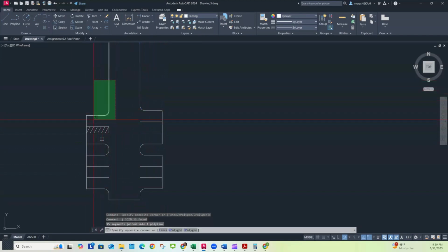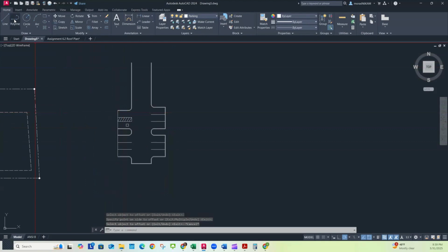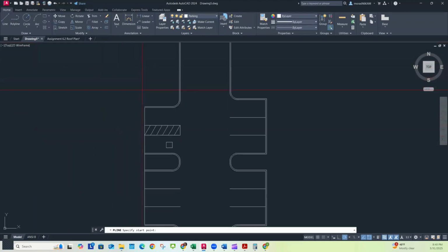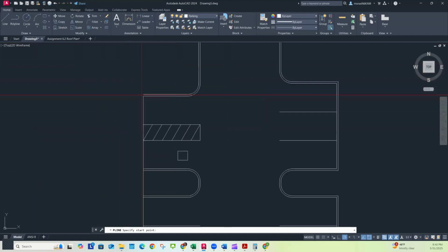And these ones. And this one as well. And I'll do offset. I'll put like a little 6-inch curve there. Okay. So I'm going to take this and I will offset it out away from the parking stalls. This one too. And this one. And I'll go ahead and add the sidewalk. So I'm going to go over 4 feet.